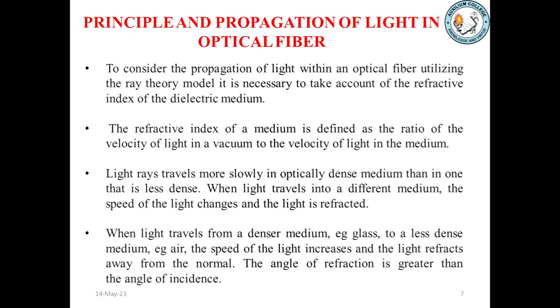Principle and propagation of light in optical fiber. To consider the propagation of light within an optical fiber, utilizing the ray theory model, it is necessary to take account of the refractive index of the dielectric medium. The refractive index of a medium is defined as the ratio of the velocity of light in a vacuum to the velocity of light in the medium.